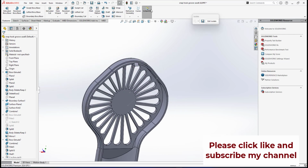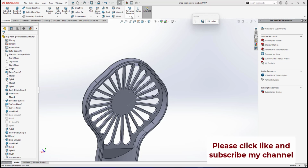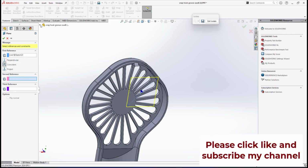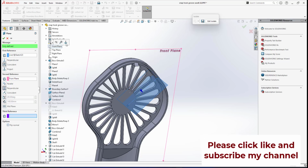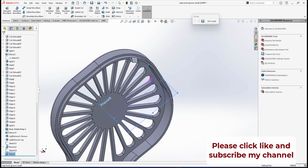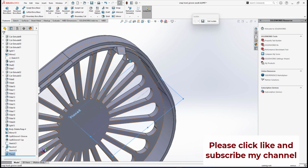So I will go to reference geometry, plane. I will select this line. The second reference will be the front plane. So I have a plane lying on that line. This is the plane on which I will create a second profile for the snap hook.